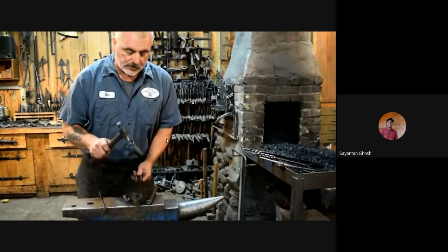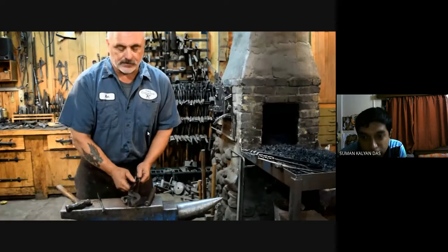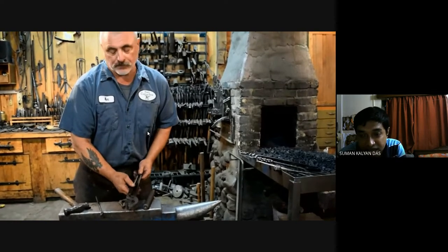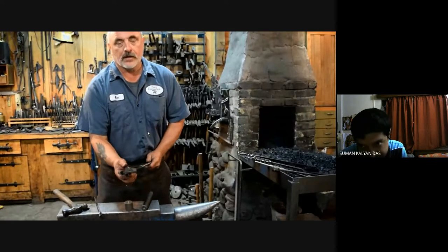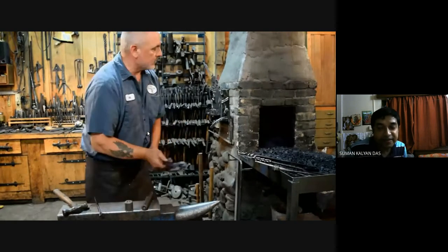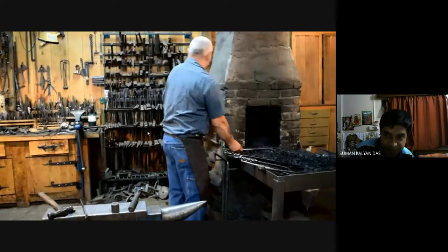Understood? While doing the riveting, obviously you can understand that finally, when the head is getting completed, the force is getting transmitted to the base plate also, and at that time the base plate may get damaged. It is for sure, isn't it? So for that, special skills and special arrangements need to be made.